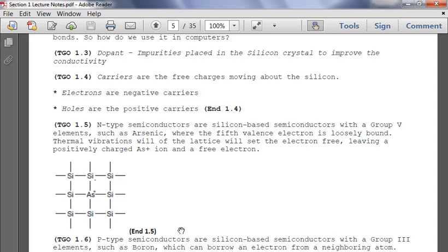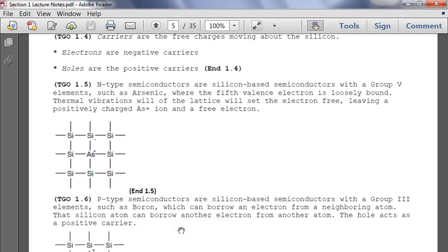And so let me read 1.6 for you too. P-type. So now we're starting to create our complements. So for our N-type semiconductors, I showed you the inverter, where the N-type semiconductor is tied to ground. So what's going to happen is you want 0 pushing these electrons away, with the negative flying away, right? So ground to the output. For 1, you want the positive, so you're going to want these holes flying through. So that's where these P-type semiconductors come in.